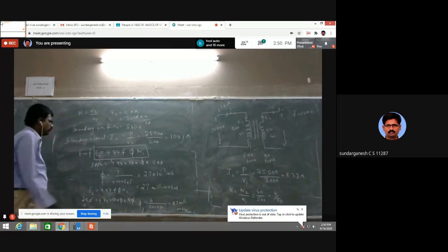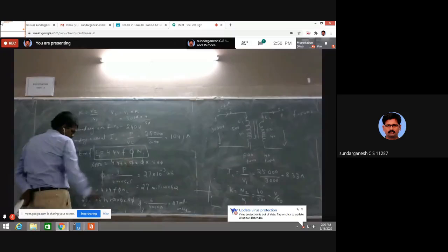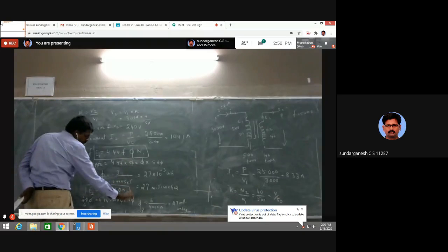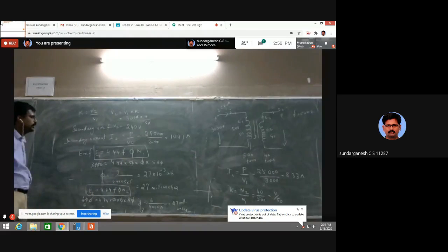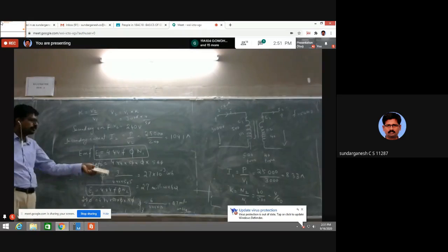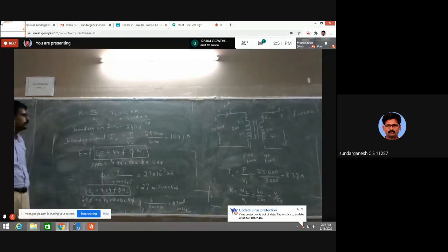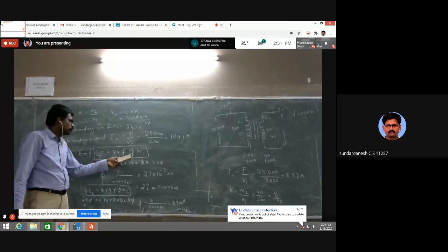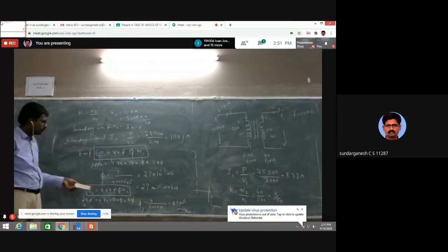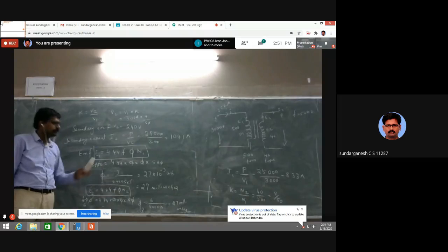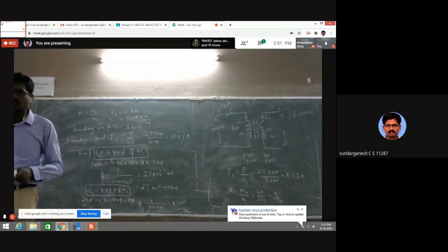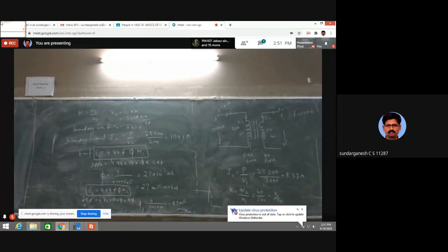Whether you take E1, then you have to use N1. If you take E2, you have to take N2. So it is not necessary that you should take E1. You can take anyone, E1 or E2. So for the final answer you have to find the flux. So E1 equal to 4.44 F phi N1 or E2 equal to 4.44 F phi N2. Write it down. After writing, put completed. We move to the next problem.